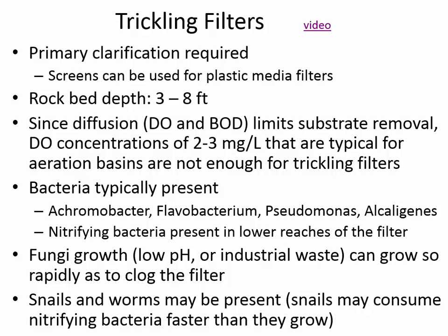One of the problematic things that can happen is that the pores between the filter can clog. And remember, in activated sludge, we're mixing the aeration basin quite vigorously, pumping in a lot of oxygen or using a mechanical aerator to stir things up. So the particles that are suspended, there's really not a risk that there's going to be a clog.